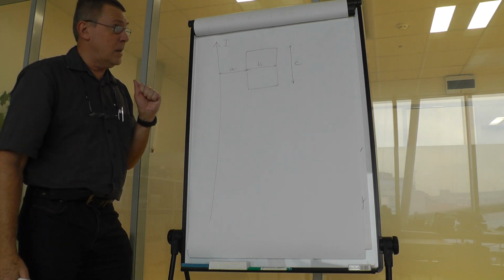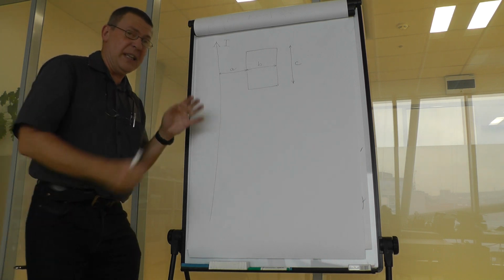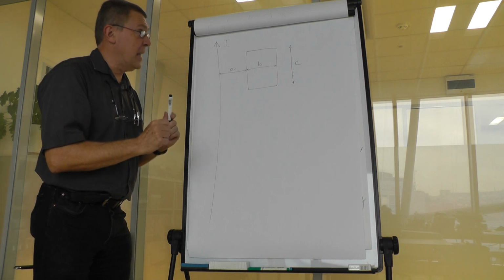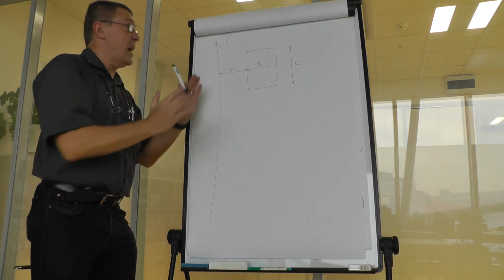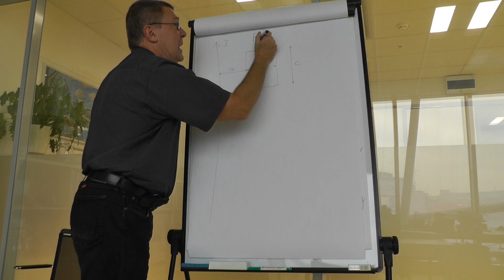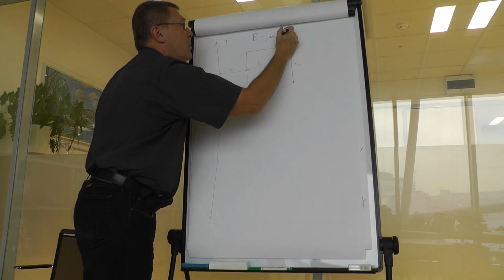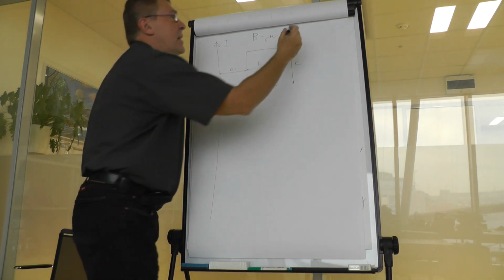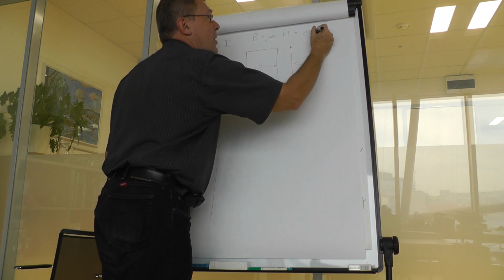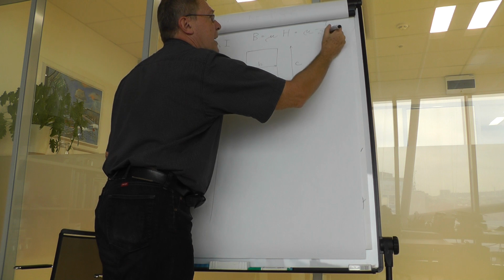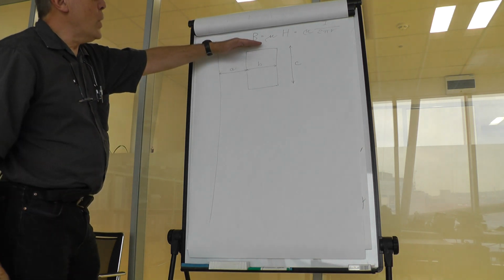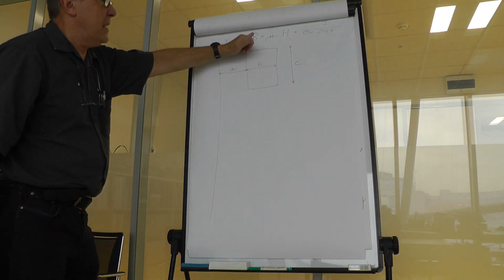We know a formula based on Ampere's law, which tells us exactly the value of the magnetic field around the conductor, bearing in mind that B is in linear isotropic media mu H, and that is mu times I over 2 pi r, just refer to our last lecture. We have the flux density.